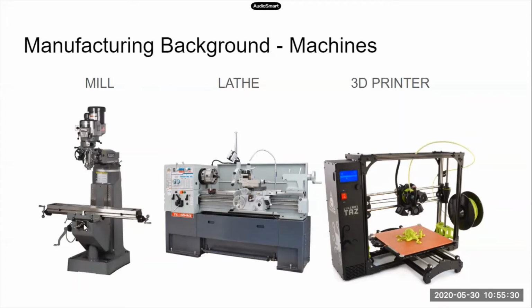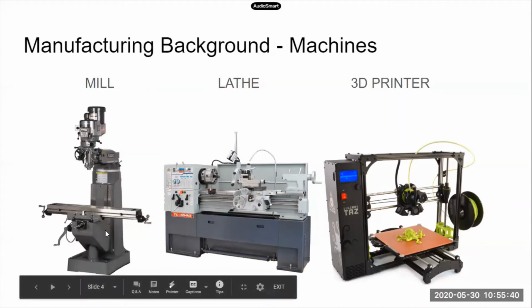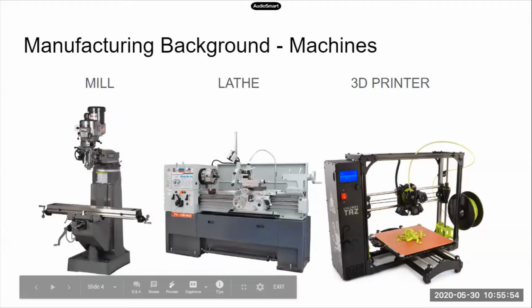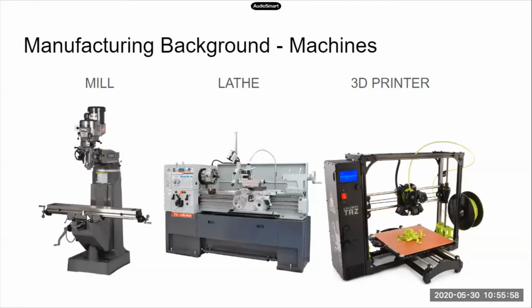And then you're going to see 3 axes here. So axes are basically how many directions the machine can go. In this case, it can go left, right, forward, backwards, and up, down. So that's 3 axes. And yeah, the tool will be spinning really fast here. You'd secure the part somewhere on this table, and then you can work within those 3 axes to create what you want.